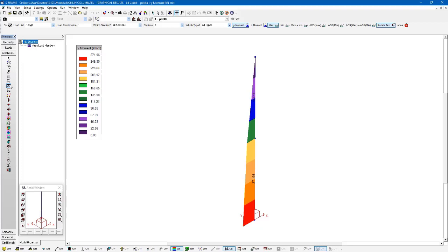Through experience, you're going to get more and more efficient at this process as well. So you may have the ability to actually know ahead of time approximately how many load increments will work. But we recommend reviewing the results, the moments, the deflections, the shears, and so on, until you notice that a major increase in the number of load increments, which increases the analysis time and so on, yields very small changes in the actual accuracy. At that point, you can say that it's probably not really worth the extra analysis time and model size to get that much improvement in the accuracy. But that choice will vary depending on the engineer.